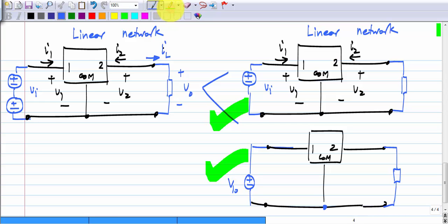Now, clearly the output voltage in this case, let us say VO1 and the load current IL1, are only due to the signal Vi, and the output voltage in this case, let us say VO2 and IL2, are only due to the DC source V1 0. Okay. So, if you compute the power that is contained only in the signal component, like I said, Vi is Vi hat cos omega t.